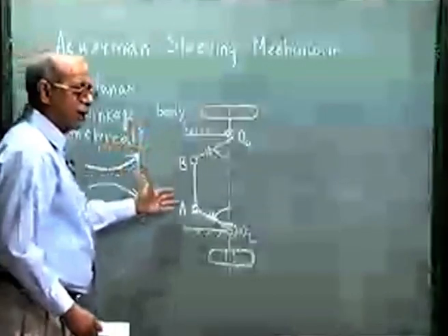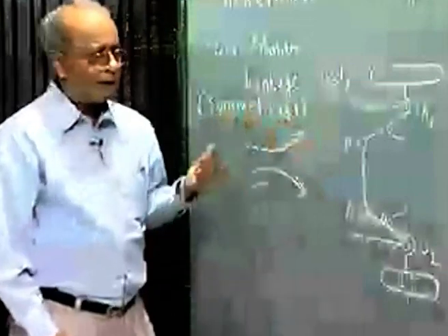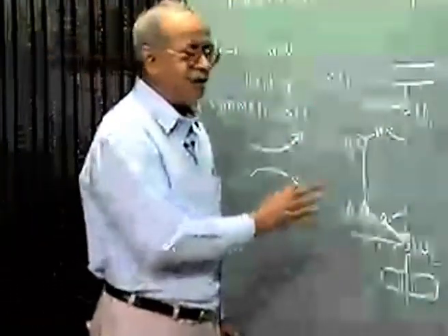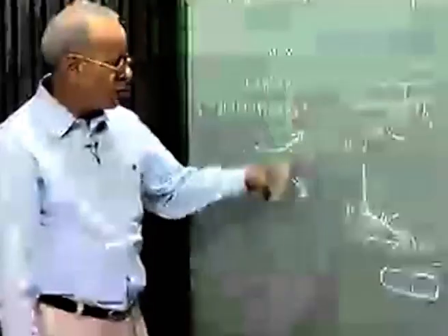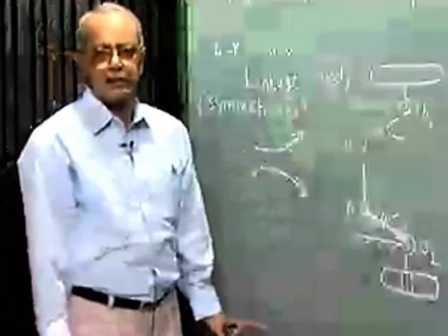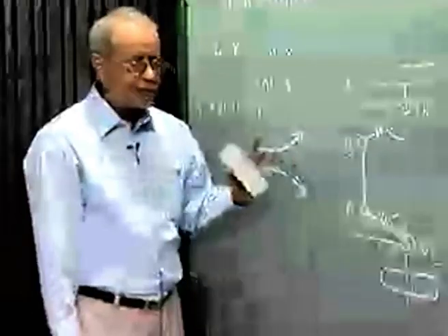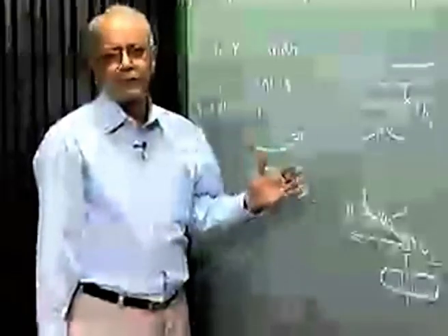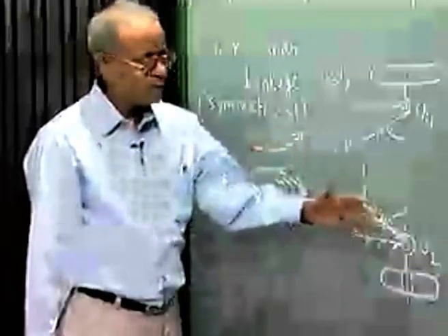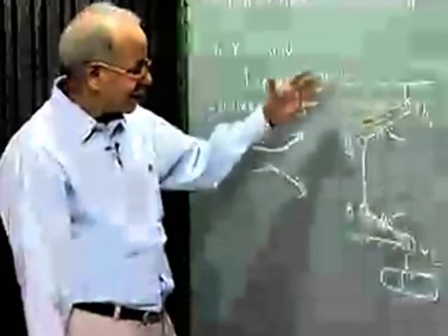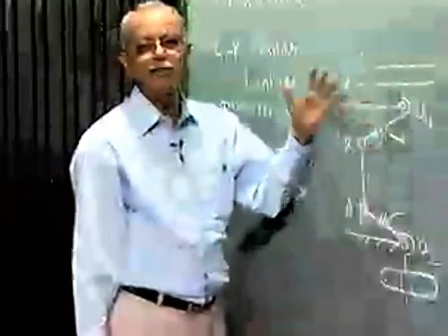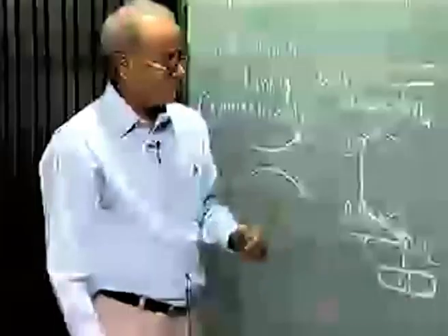Because it is simpler, we also have to pay a price, in the sense that the perfect steering condition cannot be maintained for all radius of curvature of the turns. The perfect steering condition can be met only at certain points, and we hope, if it is properly designed, that for other radius of curvature, the tendency of slight slip will not be too much.